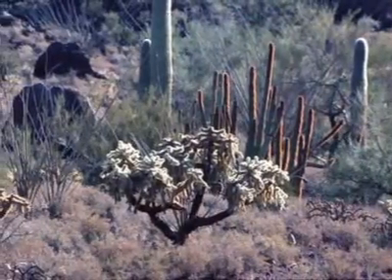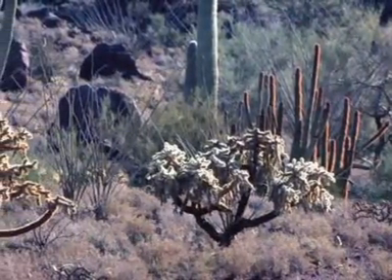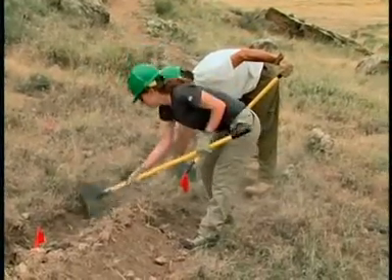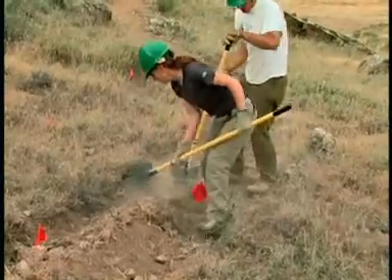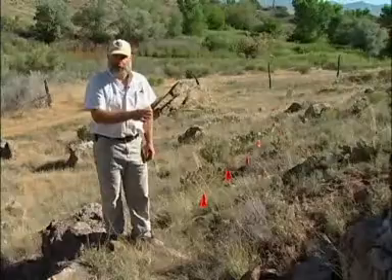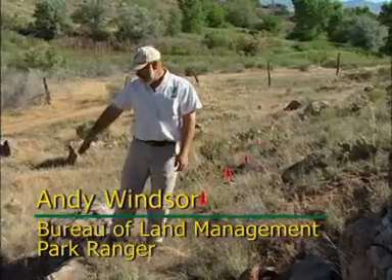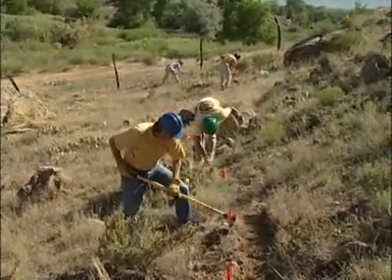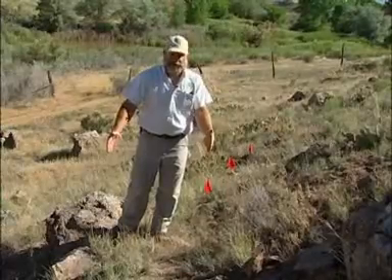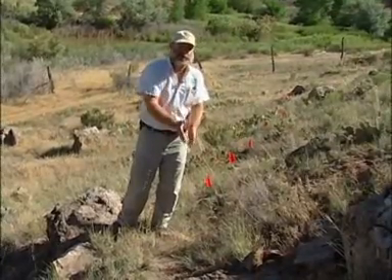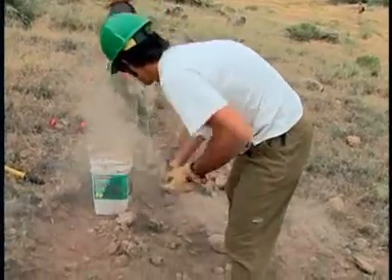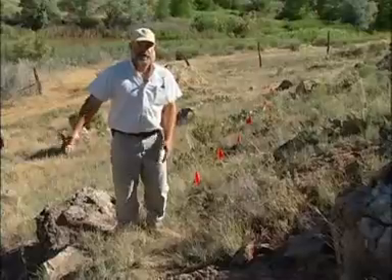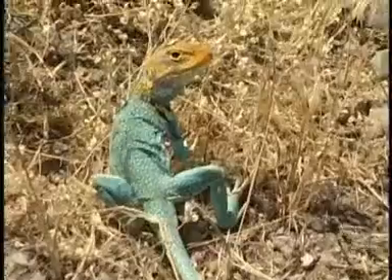In desert environments, however, plants will die if they're smothered with dirt. In these fragile places, dig the soil into the middle of the trail and haul it somewhere else. The fill dirt that we're pulling out, we don't want to have on our outslope. We'll cut from our back slope down to the center, and then from our outslope to the center, we'll end up with a pile of dirt in the center, and then bucket that away. If we try and capture the dirt on the outslope, we're going to do a bunch of damage to the delicate vegetation.